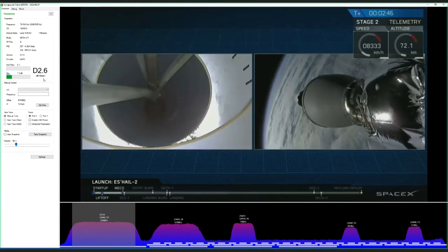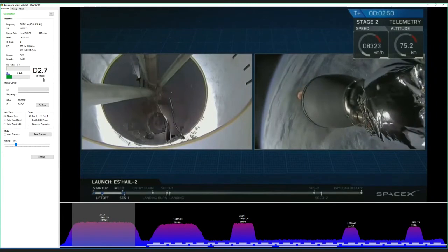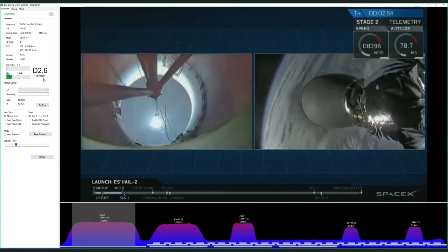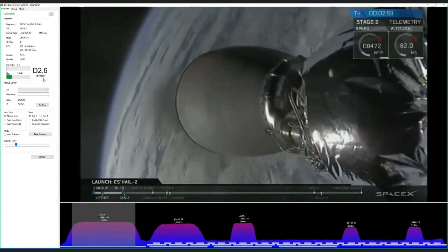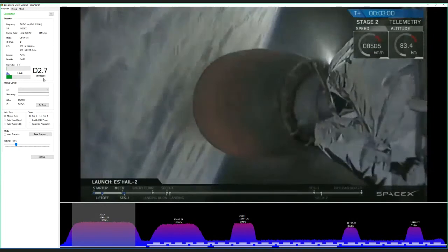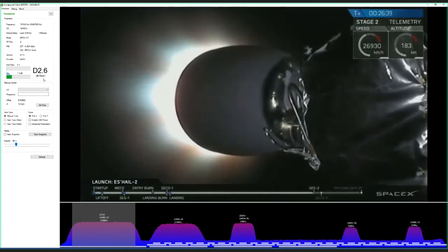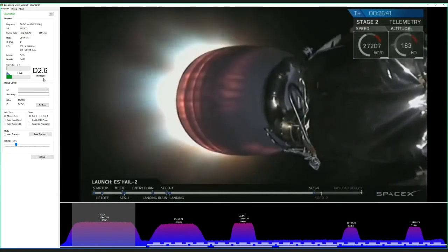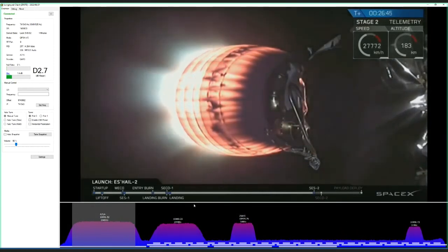Depending on the mode, you need an X amount of signal to be received, the MER. And the dB rating shows how much more signal you receive than what you require to be able to decode this video. So at the moment, I've got about 2.6 there, which means that even if it dropped down another dB, I would still be able to perfectly receive the signal without any issues. As you can see, the quality is great.